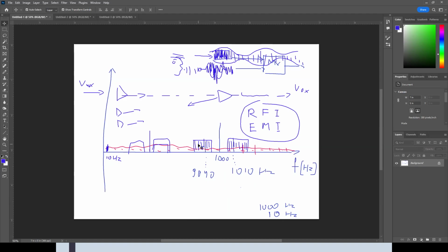So those frequencies are just not going to be heard. That's why the music on AM radio stations does not sound as clear, because some of the higher frequencies are missing. So if you overshoot the frequencies, they're just not going to be heard in the transmission.